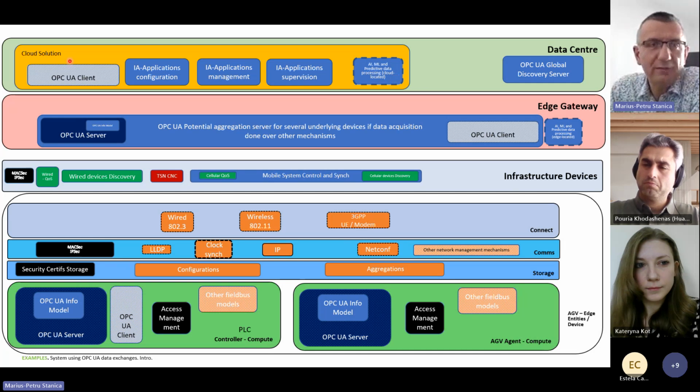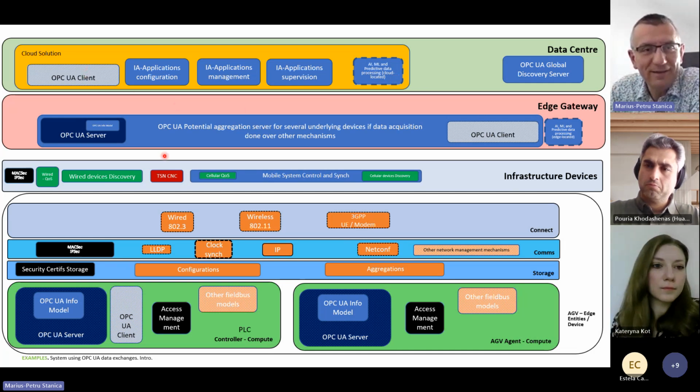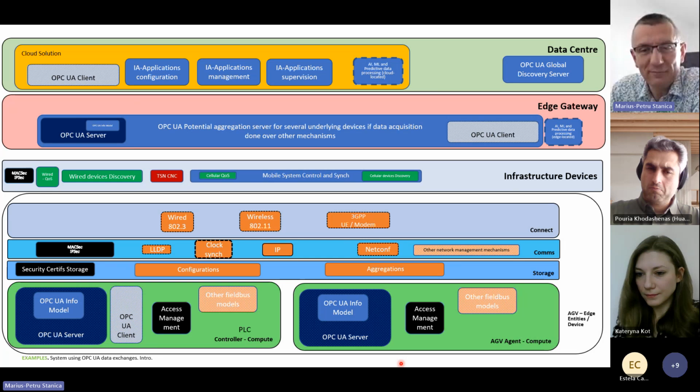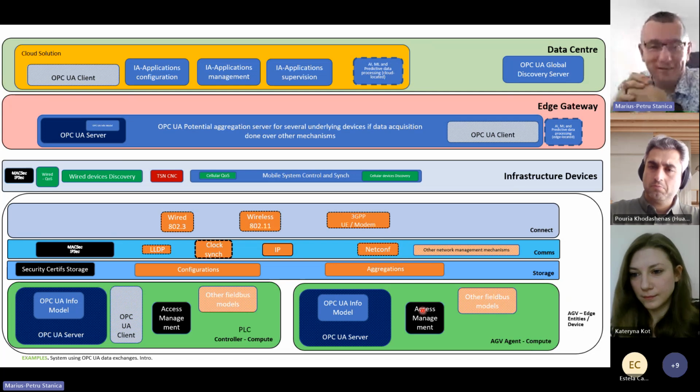So then I decide from my OPC-UA client, going over the gateway and then again to the AGV, to tell it, okay, stop, please, get into maintenance mode. In doing that, I need to make sure that my network doesn't crash or that some kind of huge alarm system doesn't come into play, and I have to take care about that information.